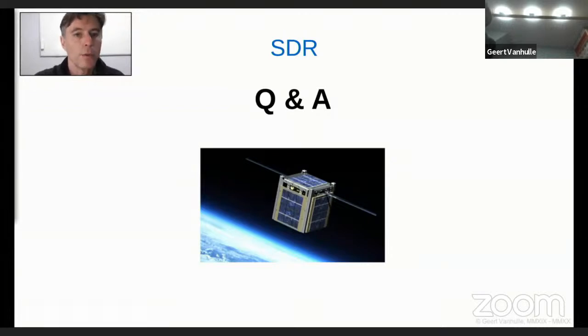So having non-FPGA blocks integrated with the FPGA is often done in a practical application of FPGA. Sometimes you have a small CPU integrated into the chip itself. So these kind of combinations are often appearing. You have AD converters that are integrated in the FPGA chip. So these kind of optimizations of FPGA chips can, of course, reduce this problem of propagation delay in a software processing equivalent of an analog circuit. I hope that answers your question sufficiently.